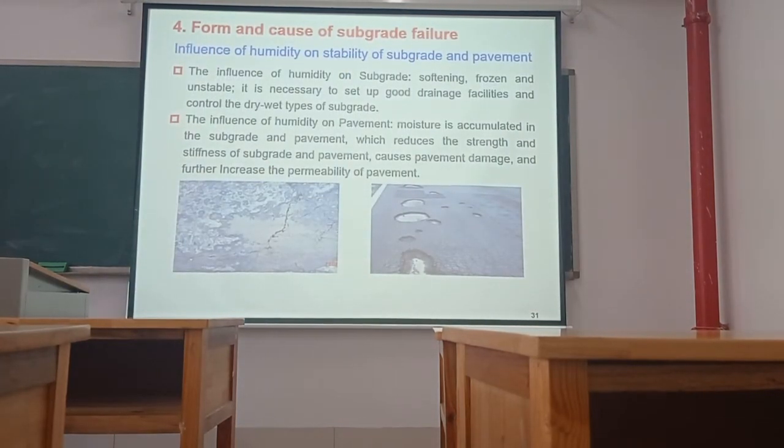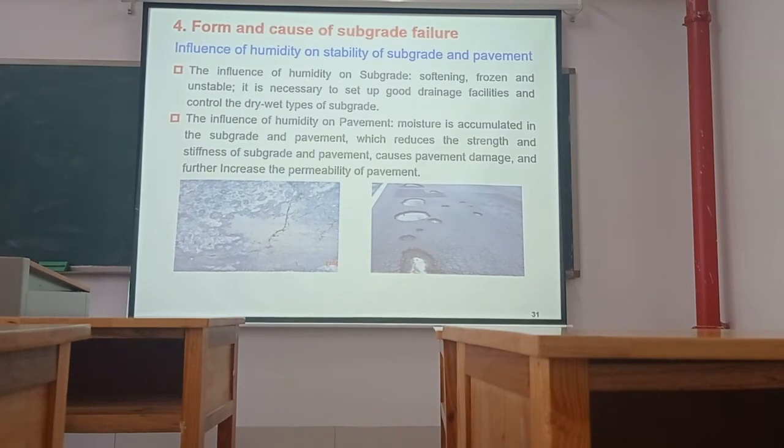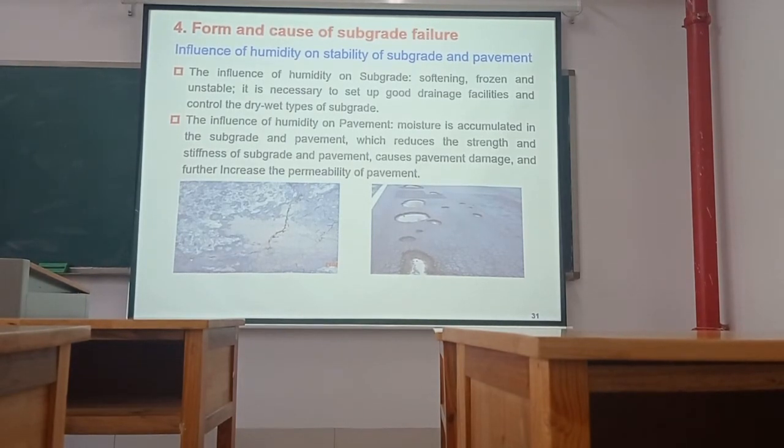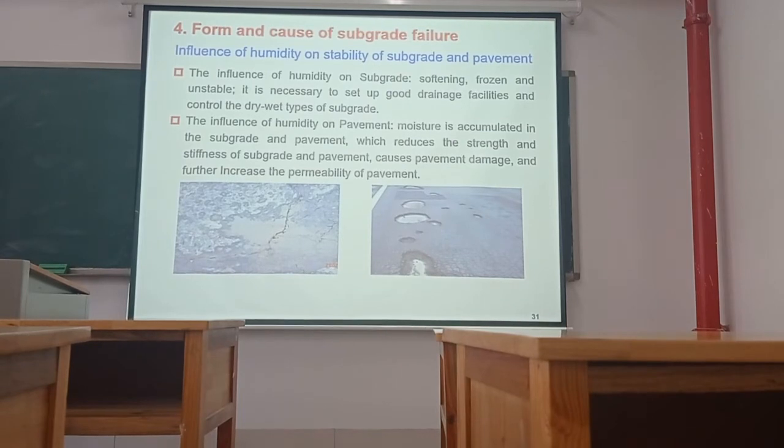Influence of humidity on stability of subgrade and pavement. The influence of humidity on subgrade: softening, frozen, and unstable. It is necessary to set up good drainage facilities and control the dry and wet types of subgrade. When the subgrade is in dry conditions, the strength of the soil is large.